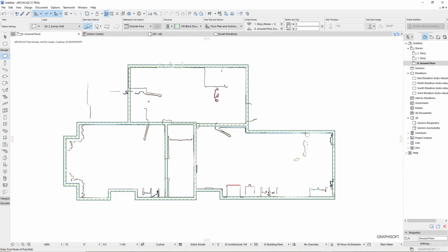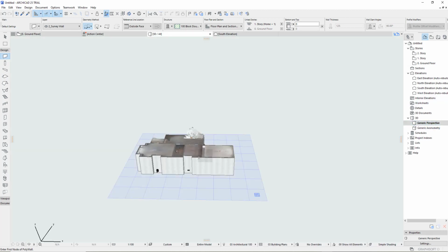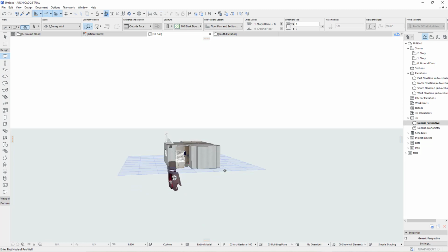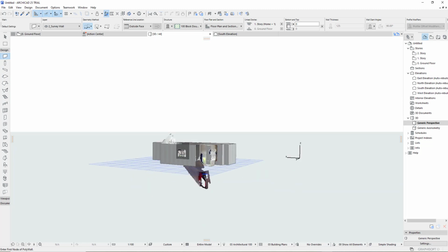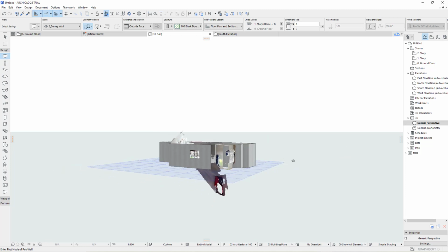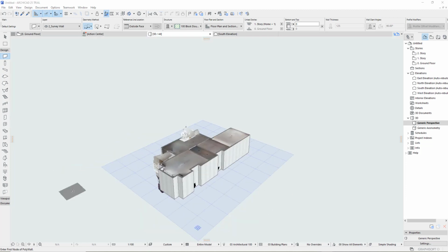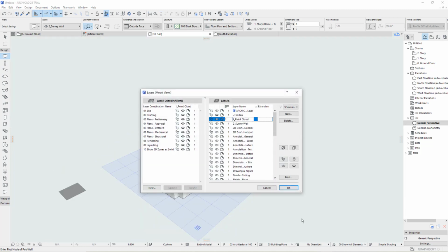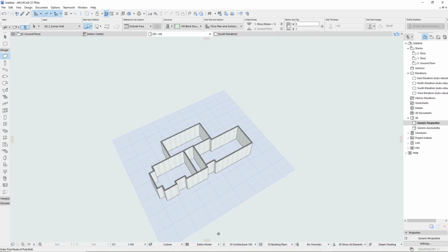So there we have all our walls completed. So we'll first go and double check in the 3D view to make sure we can see those walls. And it's good here, we can see some coincidence of surfaces that shows we're tight on the point cloud, so we've traced it rather well. Again, I can just turn off the layer for my point cloud and see that we've got everything in there.